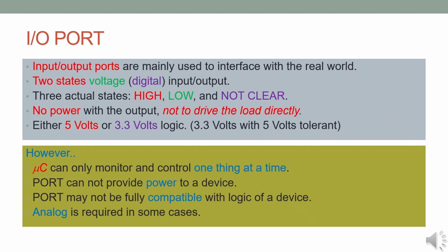The GPIO pins are designed primarily for transmitting and receiving signals, not power. Since these signals carry only a small amount of current, they cannot directly drive high-power devices such as motors or lights. Instead, we use interface circuits to safely link GPIOs with external loads. These circuits help convert voltage levels and isolate sensitive pins from potential damage.